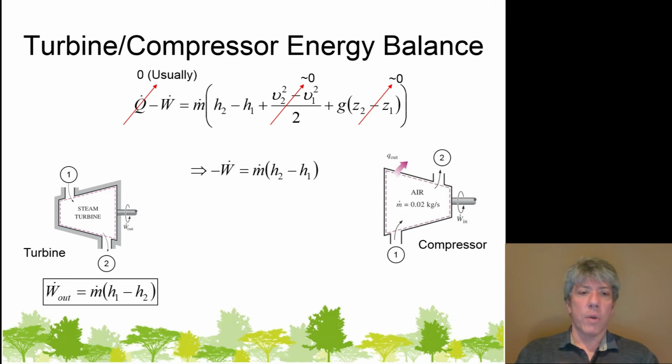If we apply this equation to the turbine and make it really clear that we're getting power out, well, let's see, power out is positive, so that negative W dot would stay as it is, but if we move the negative sign to the other side, then we'd end up just flipping H1 and H2, and there's our governing equation in the box for a turbine. Again, you'll need to find in your book where your author talks about turbines and compressors, and probably either highlight this equation or write it down, because it's useful when you're dealing with a turbine.